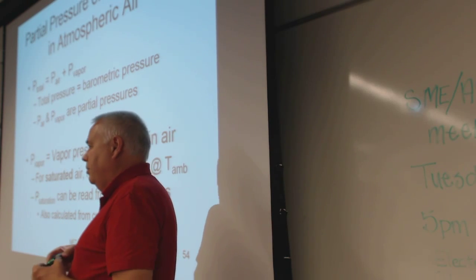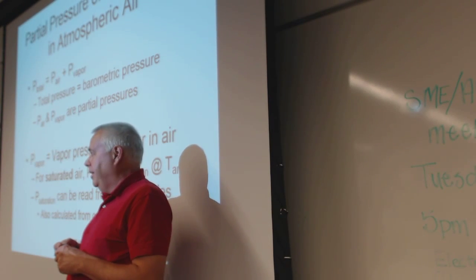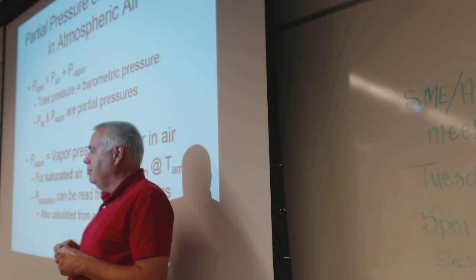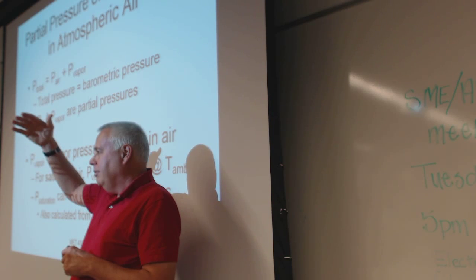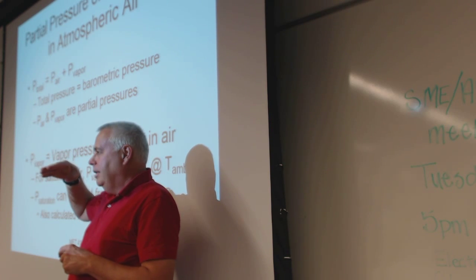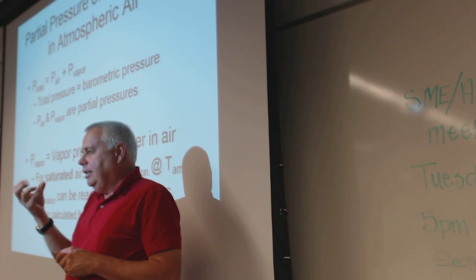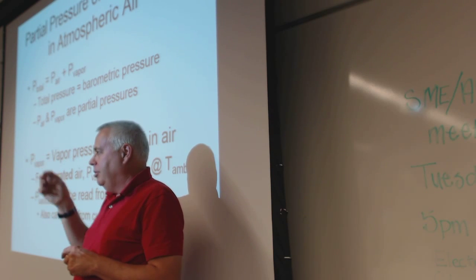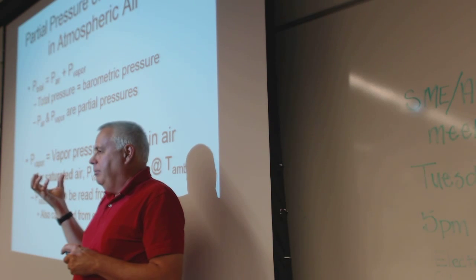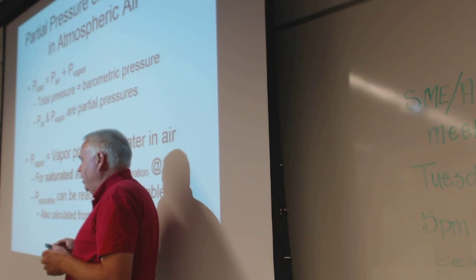Turns out most of the load for heating, and especially for cooling and for dehumidification, is the moisture of water in the air, because not only do you have to cool the water vapor down to the saturation point, but it condenses, so that latent heat is really huge relative to the actual temperature change. It becomes the largest heat load for air conditioning.